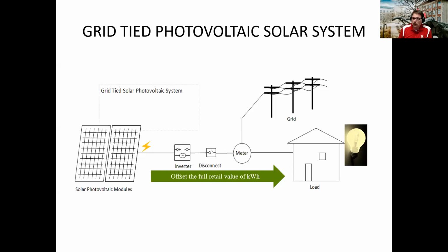Then maybe we go to lunch, we turn things off, the sun is still out, then that electricity flows from the solar onto the grid. When the solar flows onto the grid, it again goes through the meter, and they're keeping track of that. But now we have what is called excess generation. And the value of that excess generation is the detail that we need to study to make sure we understand what that value is and how much excess generation we generate. So this is where this term net metering comes in. And we're going to talk about both net metering and not net metering.